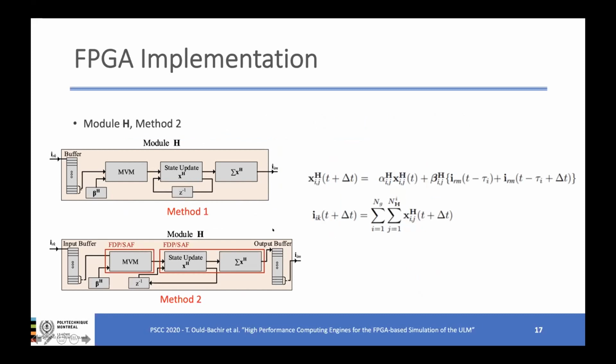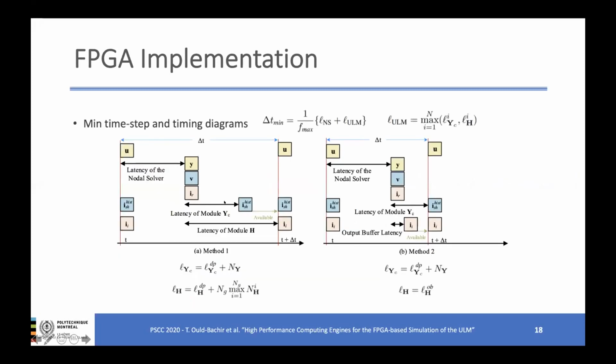However, going back to the previous slide, we cannot just use an output buffer because these delays are different depending on the mode that is being considered. So we need an input buffer that is not too large, quite small, maybe 50 samples, just to accommodate the difference between the maximal delay and the minimal delay, and then we'll handle all the samples in an output buffer. By doing so, we considerably reduce the latency, and we can have a model that is very efficient.